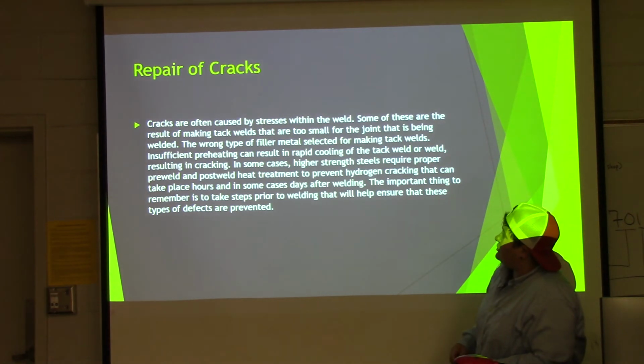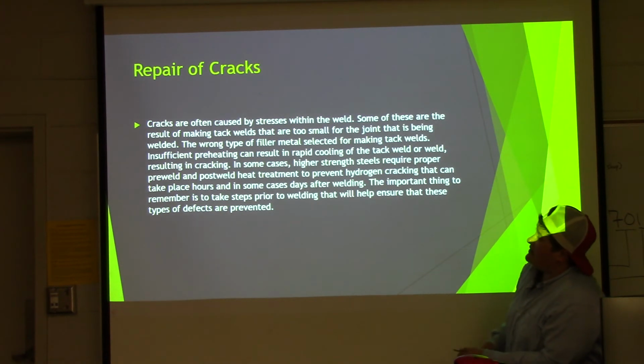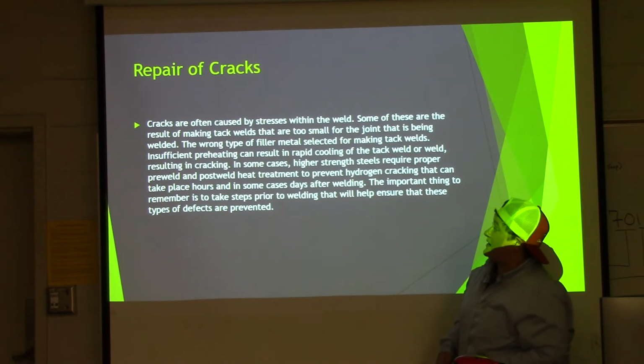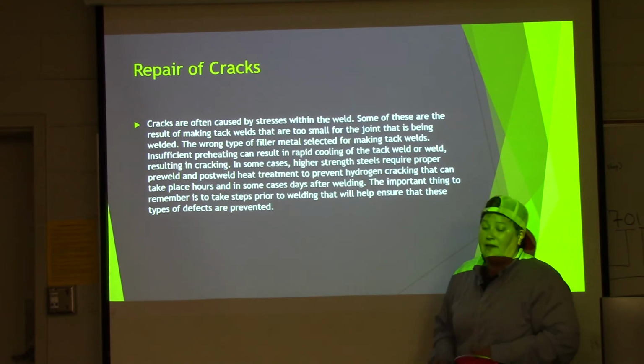In some cases, higher strength steels require proper pre-weld and post-weld heat treatment to prevent hydrogen cracking that can take place hours and in some cases days after welding. The important thing to remember is to take steps prior to welding that will help to ensure that these type of defects are prevented.